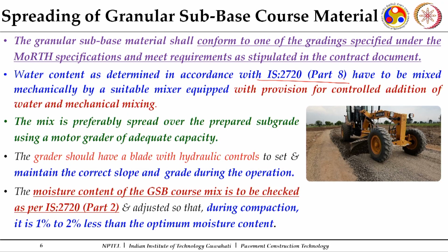Thereafter, the water content, as we determined with respect to IS 2720, has to be worked out, and this water has to be added, pre-mixed with your granular sub-base course material. This mixing can be done with harrows or rotary mixers. Pre-mixing to the required optimum moisture content is to be done, and then this is to be